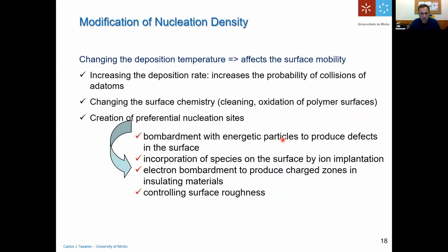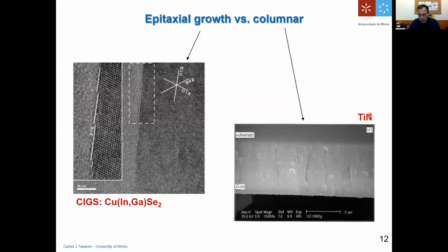of the cases that I showed you before, which is the titanium nitride, which is used, like I told you before, to make coatings on tools, for example, on screwdrivers, on drills, on other tools that will endure a lot of wear, okay? And so you have to have a very hard coating on top of the steel. So in order to render it more sustainable, the working time of this tool can be extended. And you cannot really make the deposition of titanium nitride directly onto the substrate.